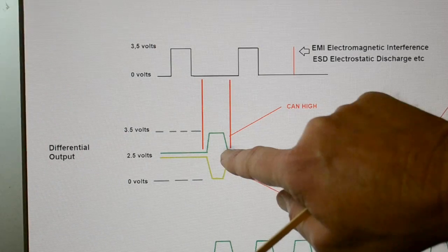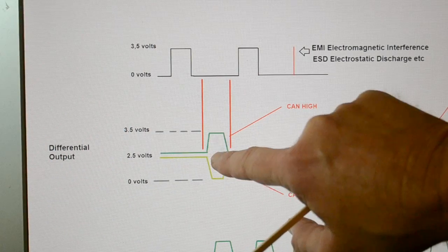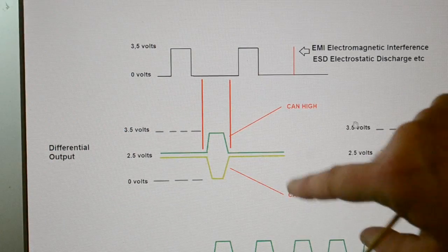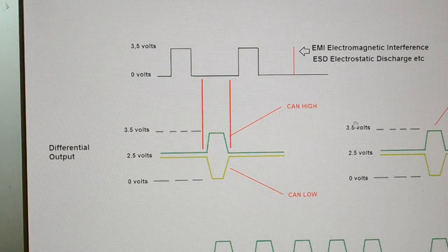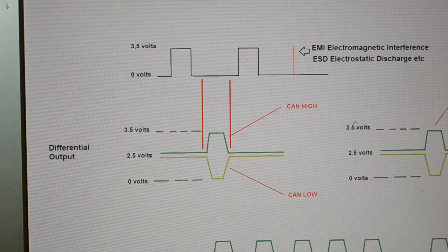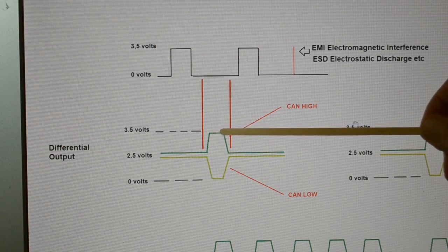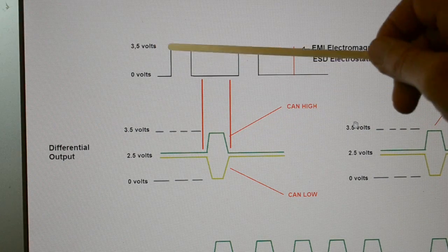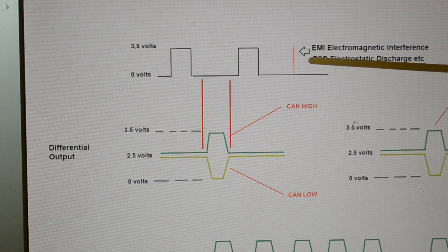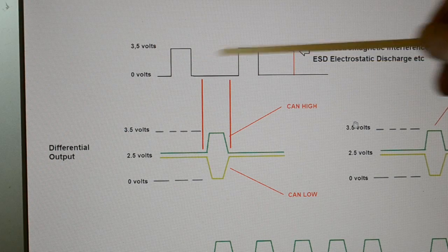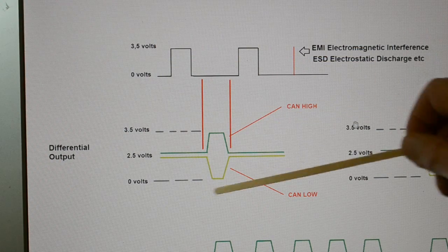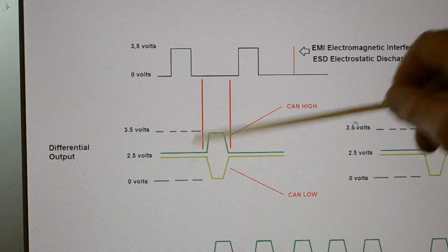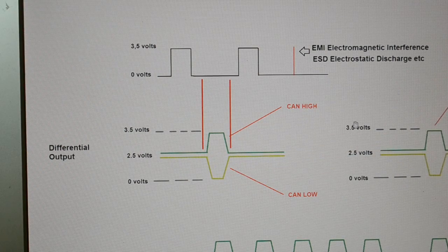So you've got to get your head around that first of all. Normally that would be a 1 and then that would be a 0, but on a CAN line it's back to front, inverted. So hopefully you know why Mr. Bosch came away from this method of communication, which on a vehicle is pretty unreliable, and he designed or invented this method, and it's very reliable.